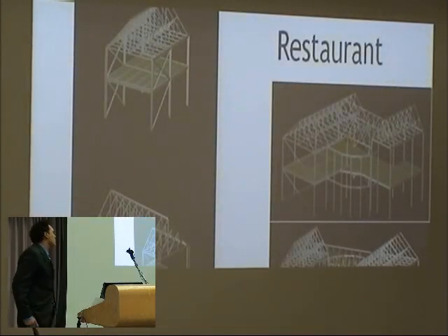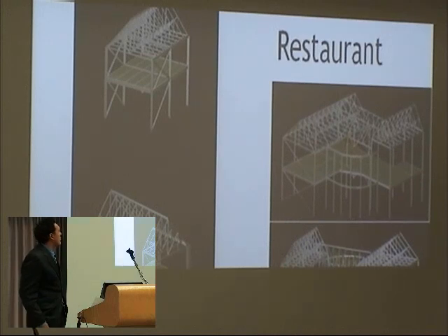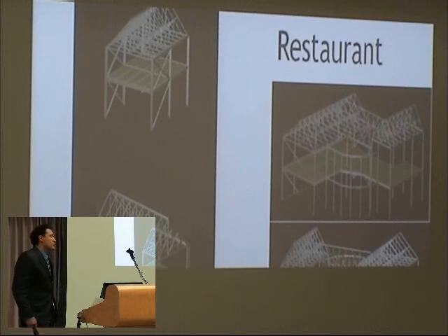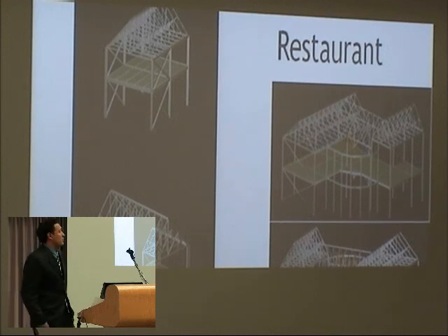Here we have some renderings from Bentley's RAM Elements. On the left side, we have the condos, and on the right side, we have the restaurant. First, we had to determine the loads. We followed ASCE 7-10 requirements. Through those calculations, we determined that the wind loads would govern.